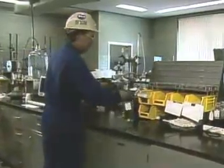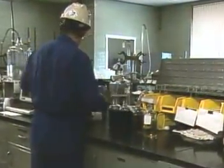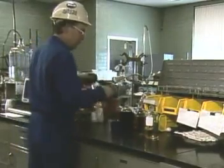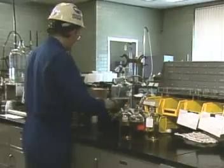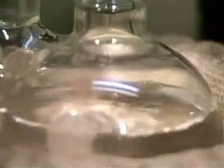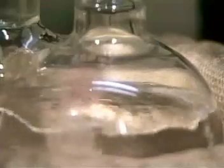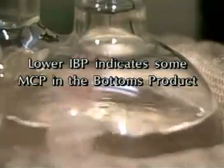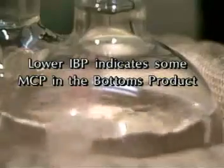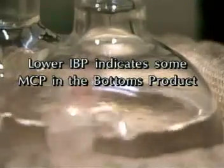To help maintain product specs, samples of the products are taken and sent to the lab on a regular basis. Indirect composition measurements are then performed to determine the percentages of MCP and CYC6 in the products. Distillation tests are run on the products to obtain their initial and final boiling points. If the initial boiling point of the bottoms product is lower than normal, it indicates that there is some MCP in the bottoms product, so the bottoms product is off-spec.